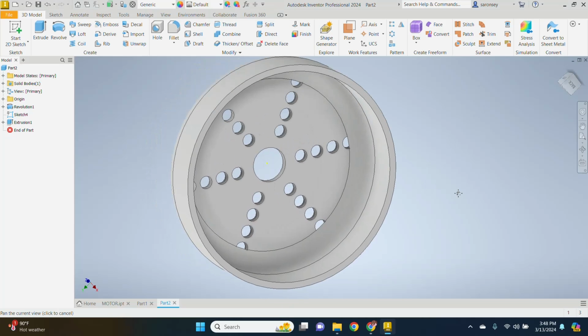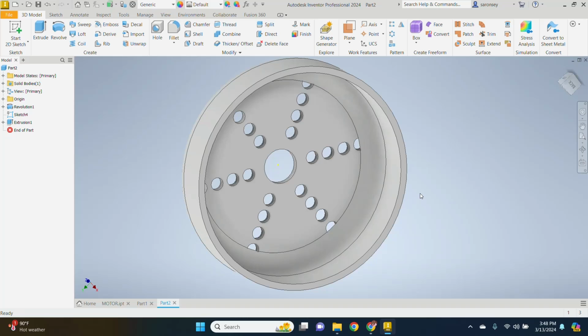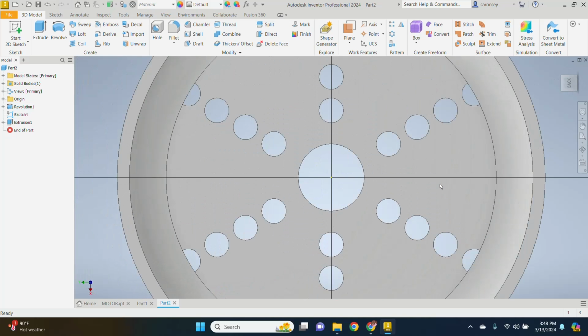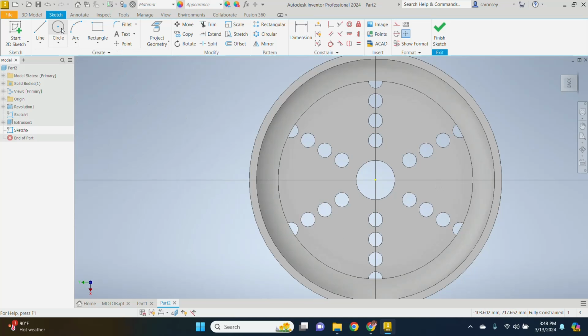Let's continue our sketch by creating the body on which the ribs will be built on. So let's select this face, sketch, choose the circle command, draw a circle from the origin all the way, or a circle of diameter 165 mm. Press enter, right click, OK.